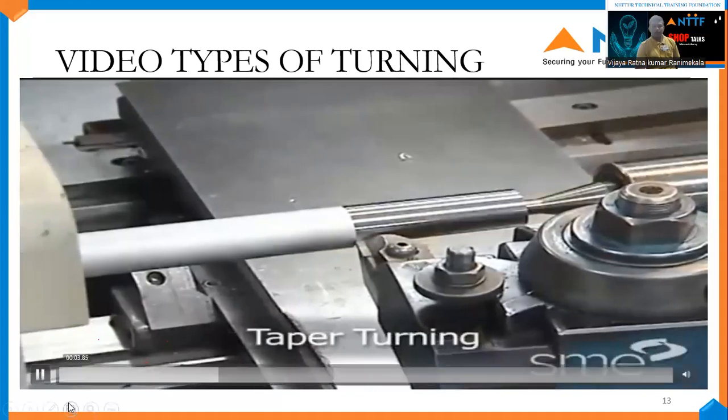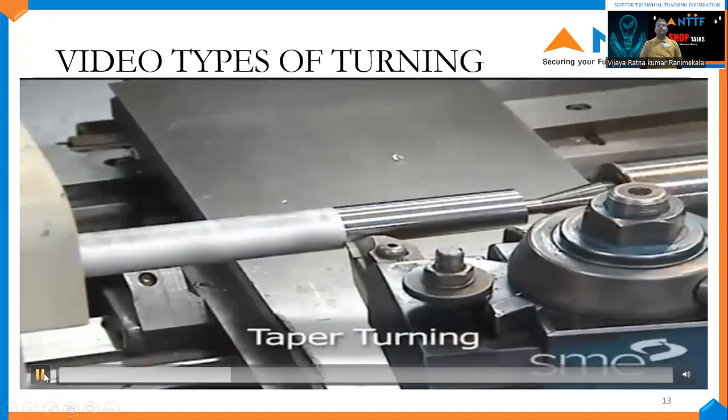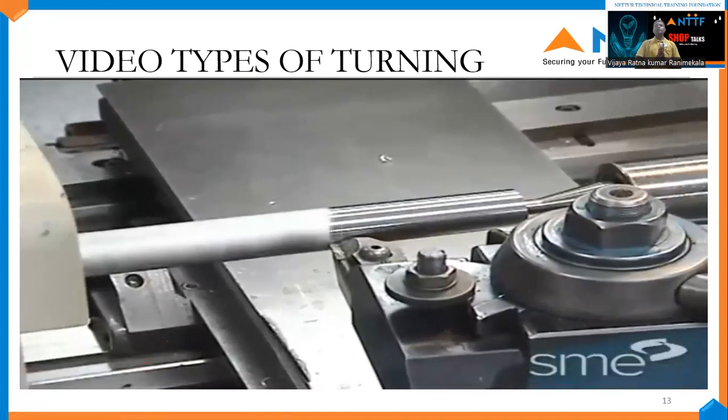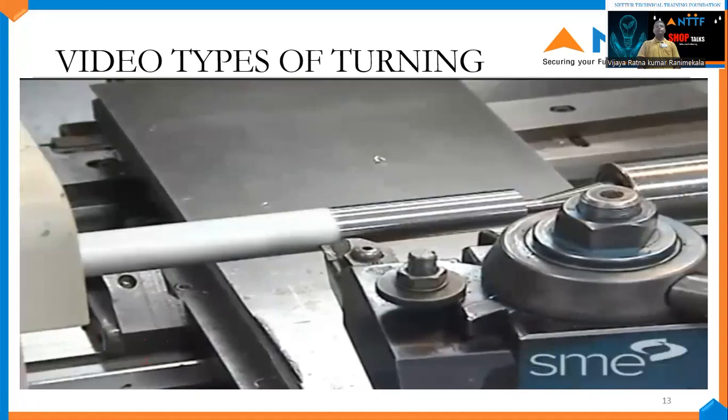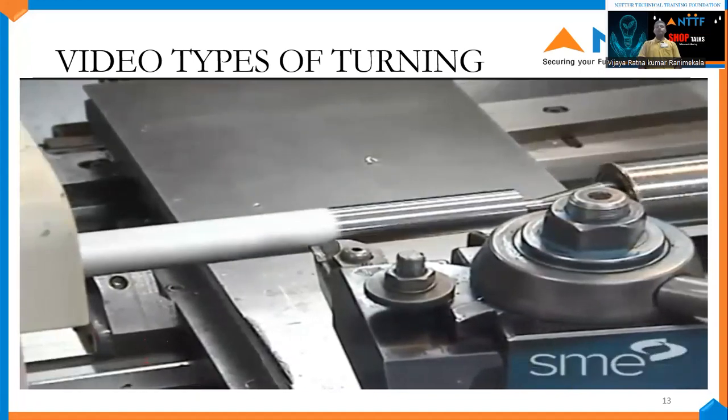Taper turning produces a taper along the axis of the workpiece. This is taper turning. This is the workpiece, cutting tool. The cutting tool must be made of high-speed steel. From here to here, we are seeing the taper on the workpiece. Tapers are produced by offsetting the tailstock from the center line or by using a taper attachment. Short, steep tapers can be turned using a compound rest.